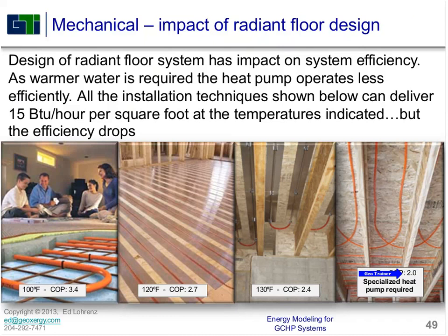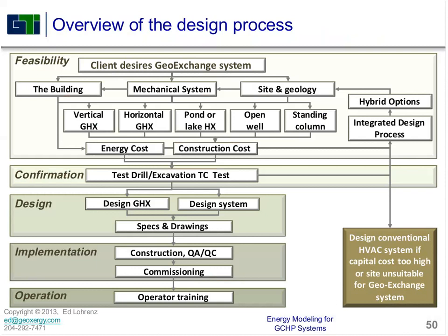And if you're going to need to supply 145 degrees, you're going to be looking at a much higher compression ratio on the compressors. It's going to make a difference on how long the compressor is going to last as well. So basically, those are some of the things that we will look at when we're doing a system design, looking at what the building is, how we can make changes to the building or the mechanical system to have an impact on the whole rest of the system.